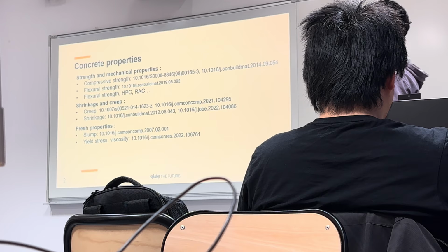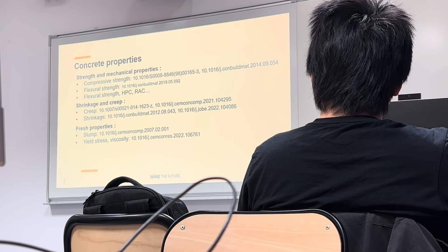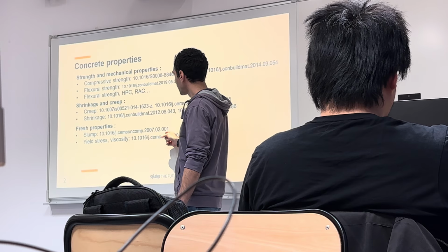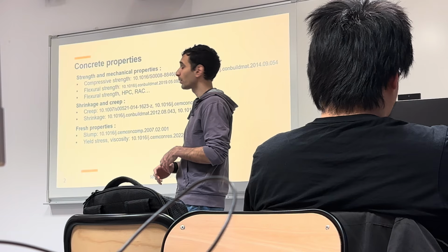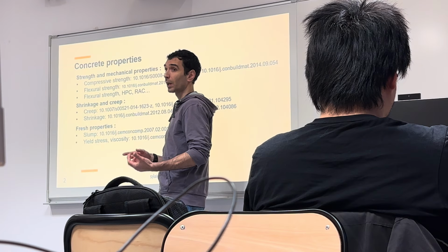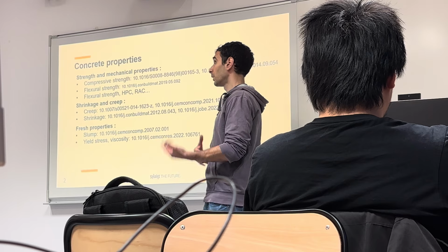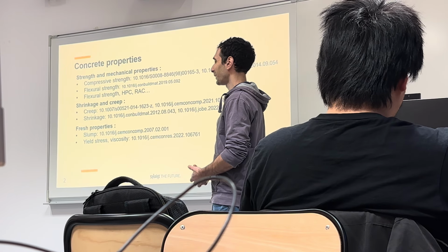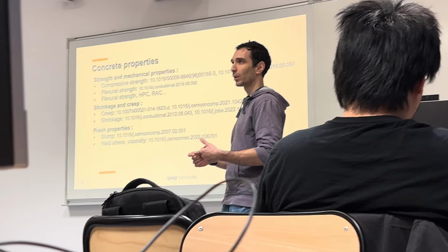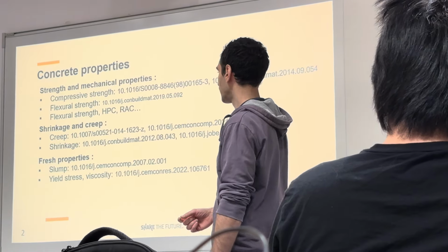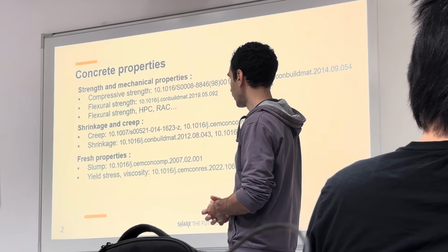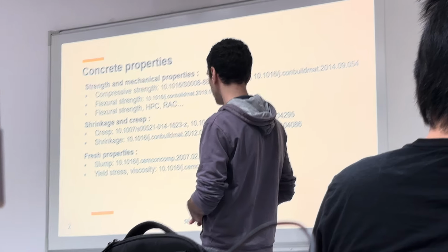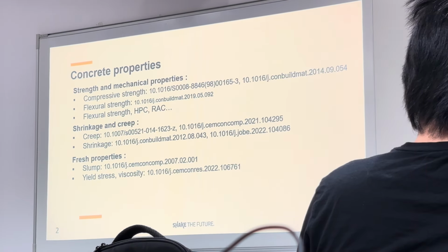Other people focus on fresh properties. Some people try to predict slump or this kind of fresh properties only based on the mix properties, for example. Some other people use cameras in mixers so that to eventually adjust the concrete mix during mixing so that we can better get the right fresh properties. So I just reported 2 references, but now there's many, maybe tens of references.